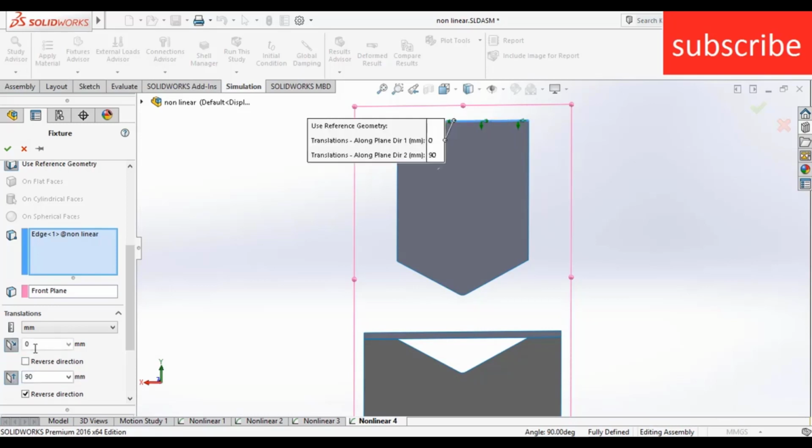And here select angle plane direction, make sure it is 0. So a question arises in mind, what does this do? For example, when this body falls, I don't want that it moves in x direction or in the other directions. So when I type the value 0, it can only move downwards. Because I click the direction 90, it can't go upward, it only goes downward, not in x directions.